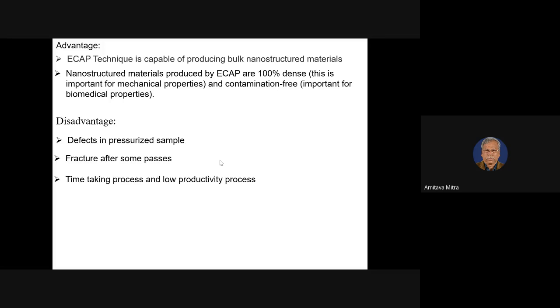But there is also a disadvantage. When there is an advantage, there is also some disadvantage. The major disadvantage is that it generates a lot of defects in the pressed sample. It introduces a lot of internal stresses. Due to this high deformation, the dislocation density within the material becomes very high.